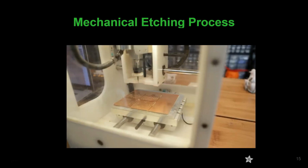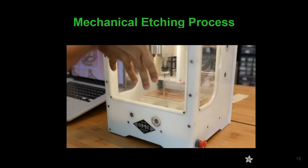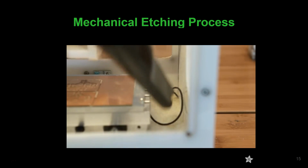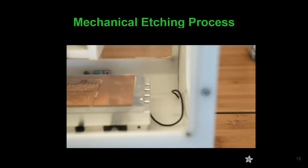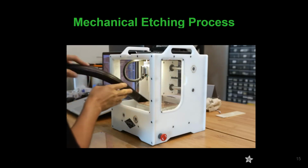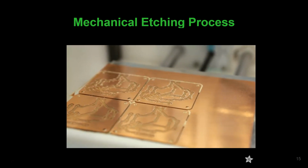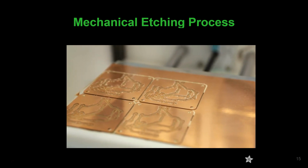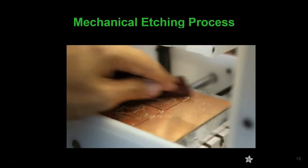The entire etching process takes around 20 minutes. When I first put the board in, I'll agitate for about 30 seconds to a minute. Then I'll leave it alone, come back every few minutes to check on it, and agitate a bit more. This one's almost done, but still has some areas in the middle that need a bit more time.